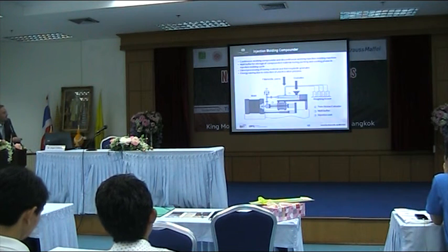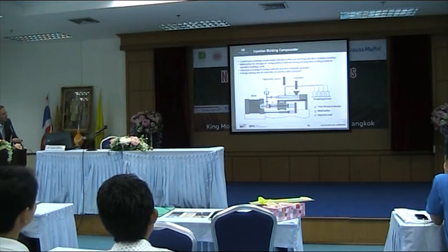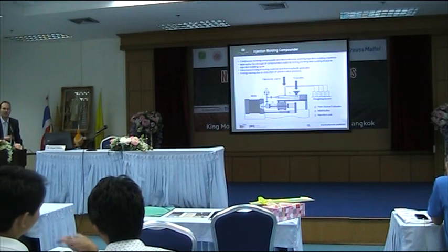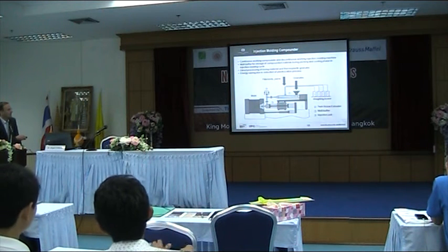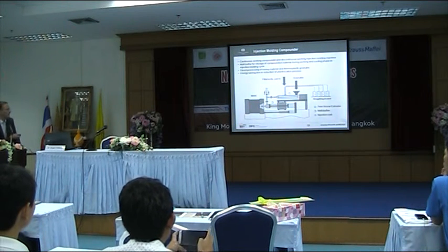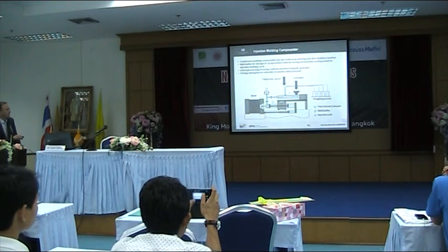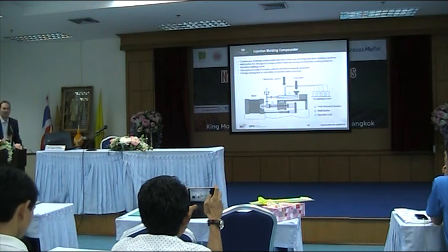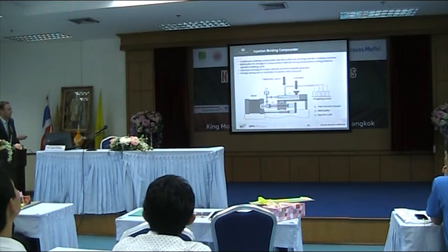You can combine it. You have a compounding process, and then go directly into the injection molding process. So you have a lot of advantage, because you are totally flexible in what you use for your compounding process. You can go inside with fibers, the typical content you want to have. You have here a twin screw extruder for making your compound, and then you have such a melt buffer, because the compounding process is always a continuous working process. Injection molding is discontinuous, because you have